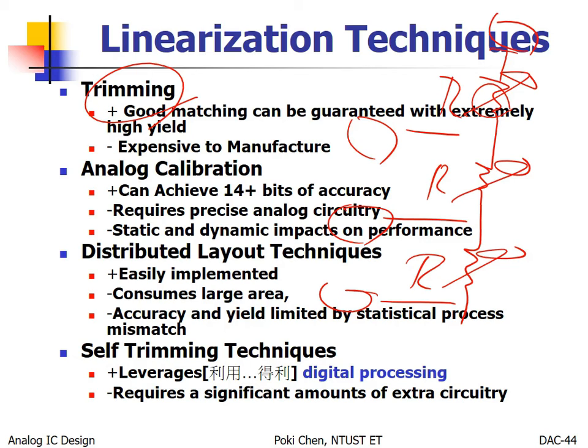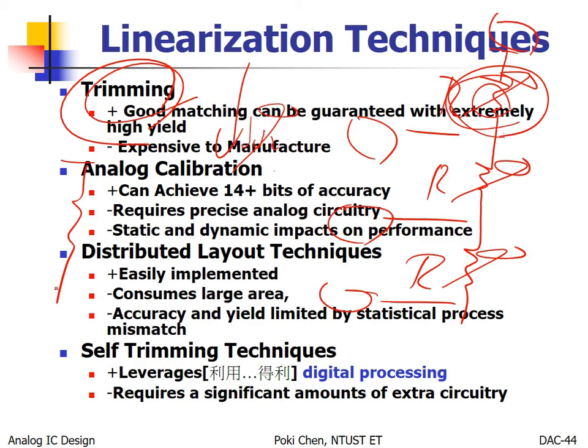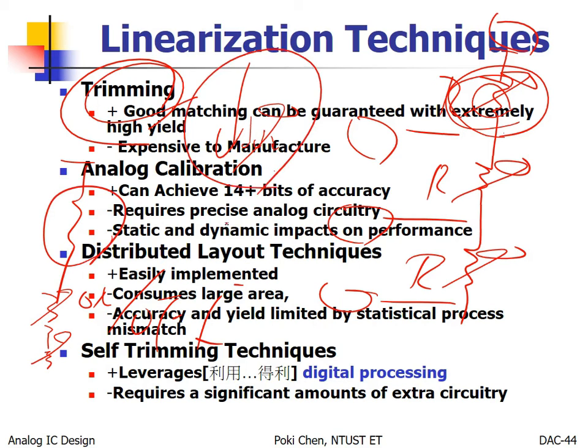And how about the current? The same, right? You have current, and the larger one, the smaller one, then you can fine-tune it. Anyway, for any kind of trimming or calibration, we don't make all of them available. For example, for this one, you have an always-on resistor, then the smaller one to be on or off. This is always on, the base resistor.